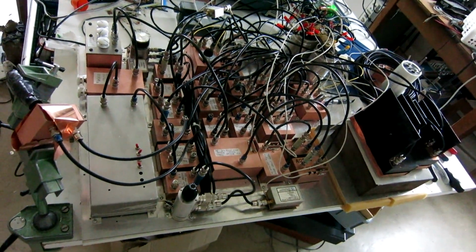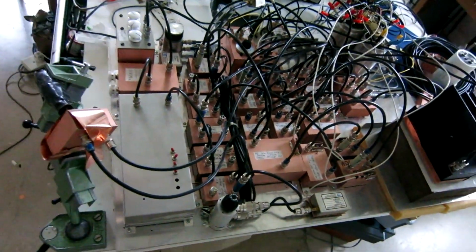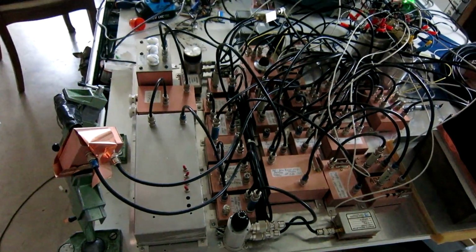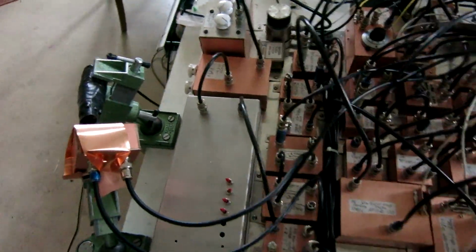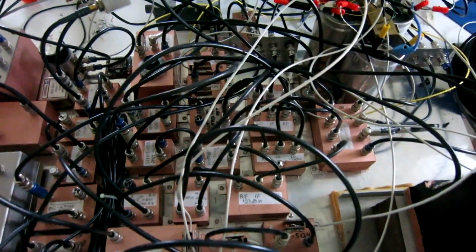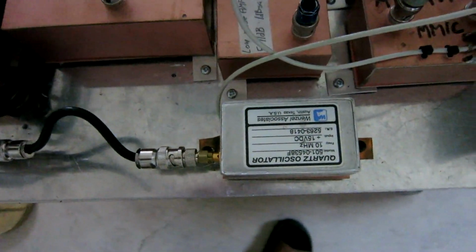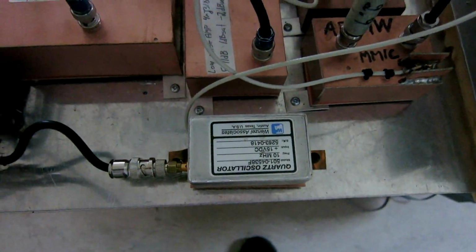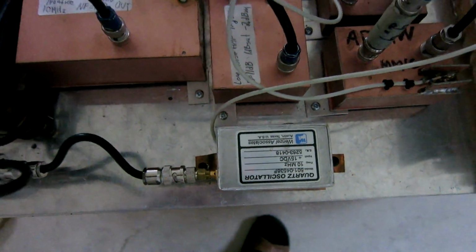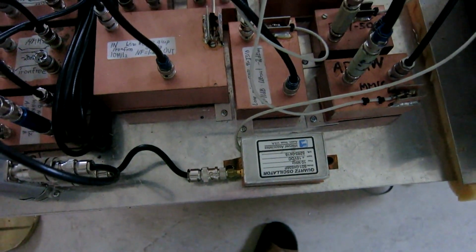In this video I'm going to study noise in crystals, quartz crystals. And this is the setup I'm using. It is an interferometer, this part here, and two direct conversion receivers here with local oscillator here. And the signal source for the interferometer is this one from Wenzel, a low noise oscillator giving plus 12 dBm of power. I will show the schematic diagram later in this video.